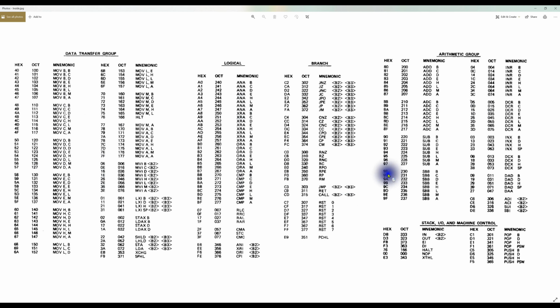This however gets into why octal is interesting on the 8080. So LXI B, a register, and if you look at the LXI bits here, let's see, in octal, it's a 001. Actually, that may not be a good example. Some of the opcodes break down really easy in octal, where you can just look at the bits and know what the opcode is by the first 2 bits, and then what it works on against the other bits. And I'm not seeing some great examples pop out here.